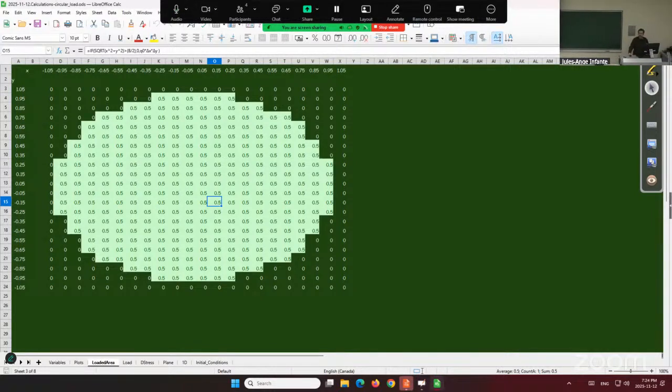So if you want to do a map of settlement when you build an embankment, you could use something like that, even if you don't want to use fancy finite element modeling for settlement, which most people don't do in practice, right? We use the Boussinesq method because it has been shown to give reasonable results for these calculations, so people still use it to this day. Okay. In terms of stress distribution.